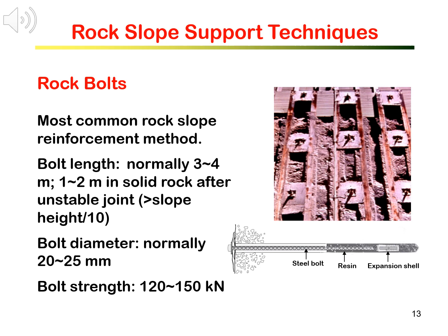Let us learn a little more about rock bolts, as this is the single most important rock reinforcement element in rock slope engineering. Rock bolts are typically steel rebars of normally 20 to 25 millimeter in diameter, which take tensile loads of about 120 to 150 kilonewton. Most of the rock bolts used for rock slope supports are end anchored to provide immediate compression to the rock mass. They are inserted into pre-drilled holes in the rock mass and then fully grouted to give a long life of serviceability.